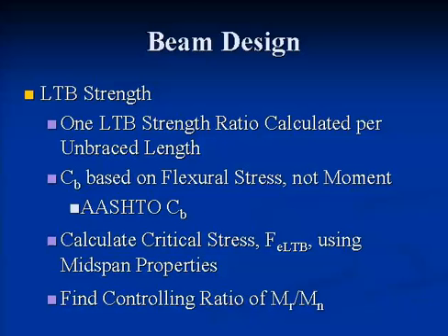The equation we're using is based on stresses, because even with constant moments, the stresses are changing, and that really defines what the moment amplification is. It's the level of stresses, not the actual moments in a non-prismatic member. And Don's research showed that the AASHTO formula was as accurate as the AISC formulation where the answer was good, and more accurate in the areas where the AISC formulation tails off in accuracy.